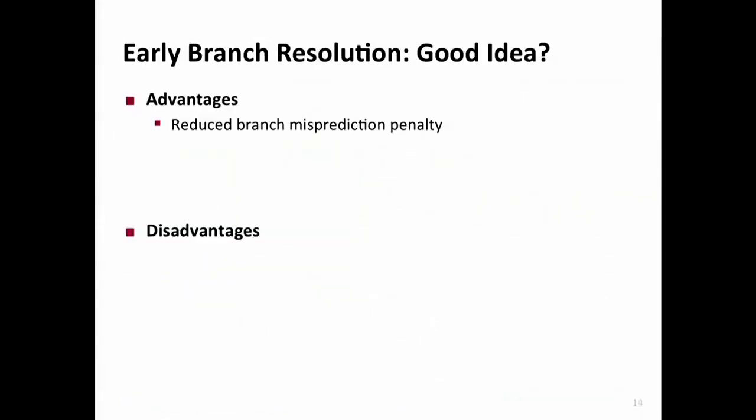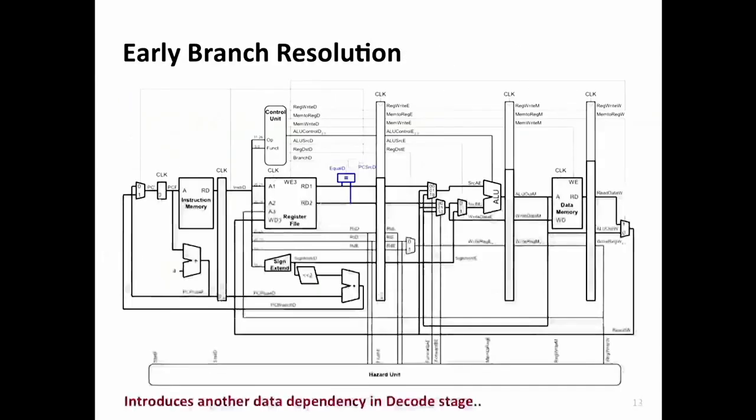which is similar to what you've seen earlier. Yes? Exactly, yes. You may have messed up your critical path here, right? Basically, now it's not only register read, but you've added an ALU operation, equality check operation here, and this may be your critical path. You read the registers and then do an ALU operation.